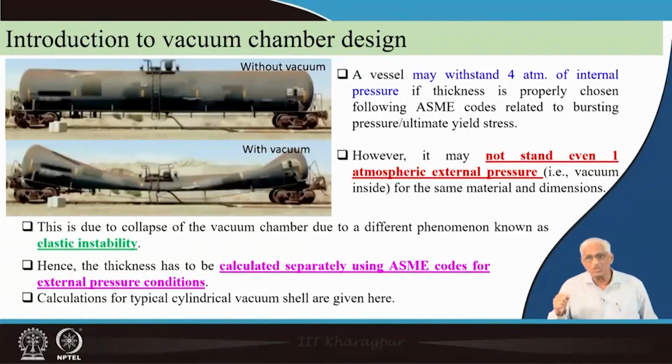For such issues, if a chamber is tested up to 1 millibar, you don't have to test it up to 10 power minus 10 millibar because of a simple relationship. 1000 millibar, that is 1 atmosphere absolute, minus 1 millibar is the same as 1000 millibar minus 10 power minus 10 millibar of a UHV unit. So with respect to mechanical force or implosion or thickness calculation, it is good enough if you test the chamber up to 1 millibar.